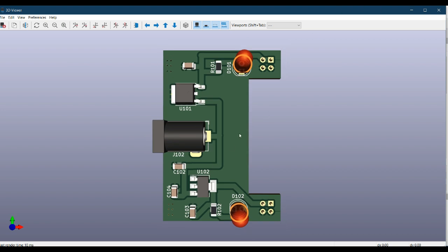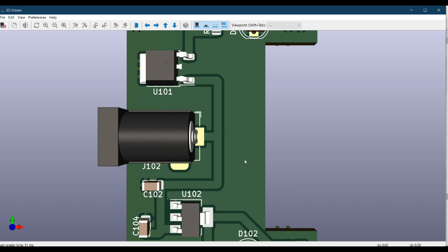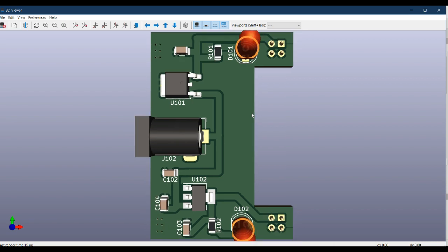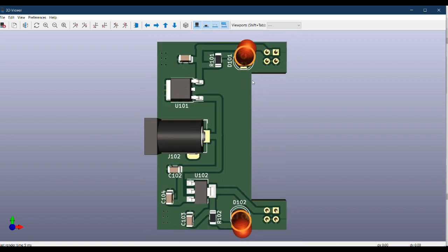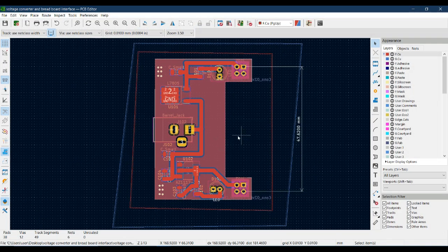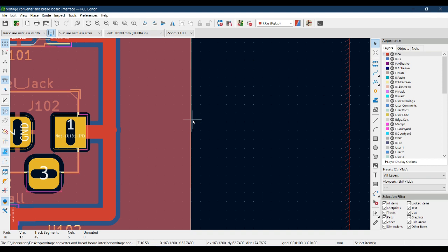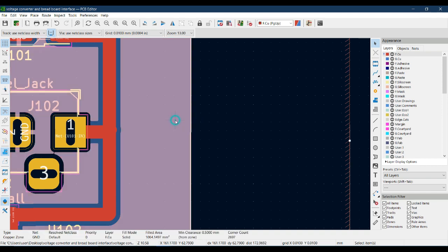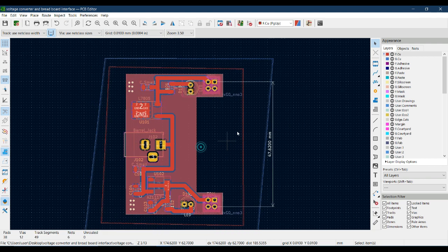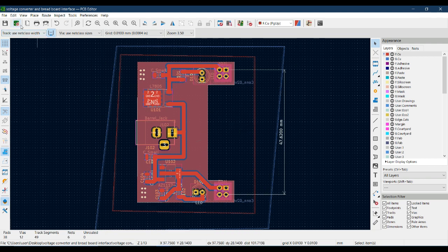Now the other thing you can see over here that our copper fill zone is at the edge of the PCB. This is not a good practice that your copper fill zone should reach the edge of PCB, because sometimes if little damage or something hits the side of PCB, this may get short with the copper fill zone. So in order to give a gap between the edge cut layer and the copper fill zone, what we have to do, we will go to board setup.